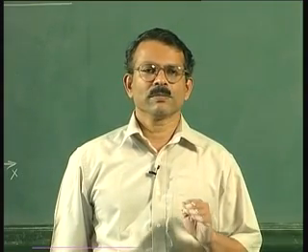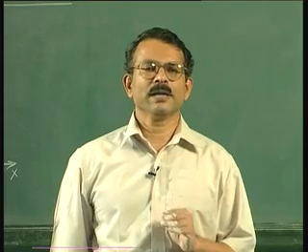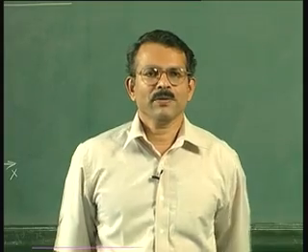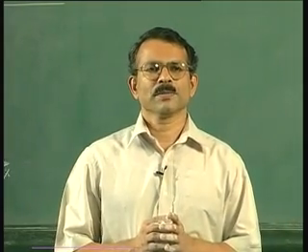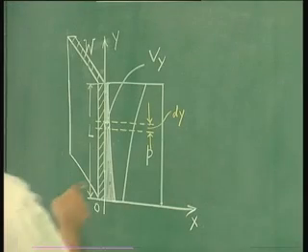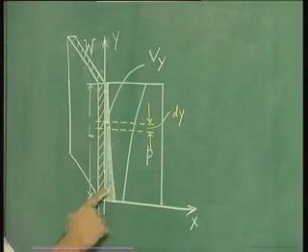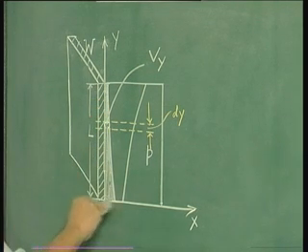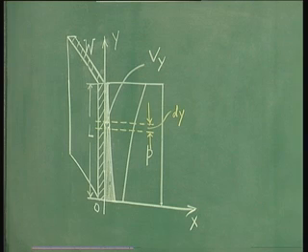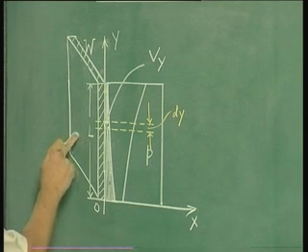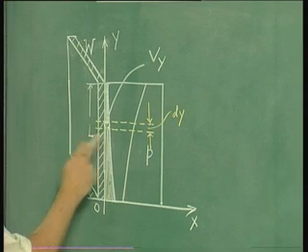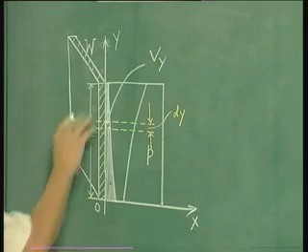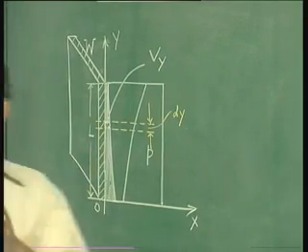One can also show similarly in a rigorous manner how, starting from the 5 basic equations, you can derive the current voltage characteristics. However, we will not follow the rigorous approach because here the picture is 2 dimensional. You can see that you have an electric field applied in the y direction and an electric field along the x direction. The x directed electric field is from the gate to substrate, the y directed electric field is from the drain to source, which enables you to pass the current.